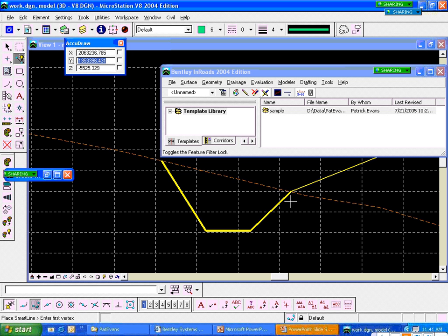After we bounce up, we're going to come in and put this ditch piece in like this, so that this point right here and this point right here are exactly the same elevation. So we're going to force this ditch bottom in here automatically. No seeking of the existing ground.